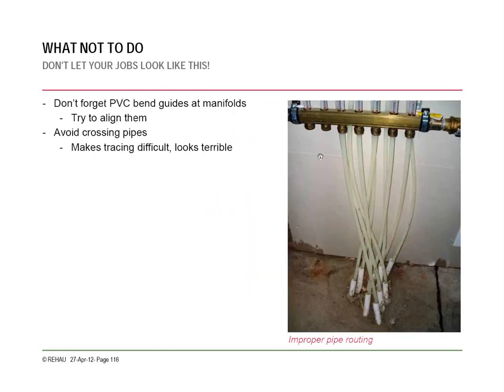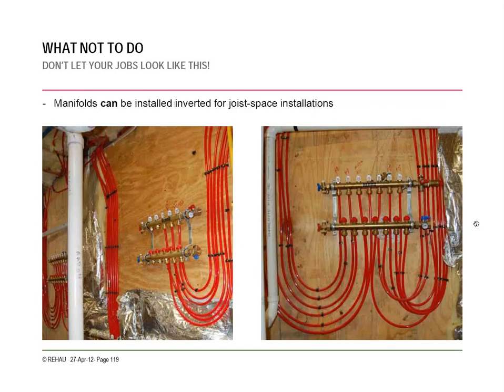Bring your pipes back in an organized fashion. Here you can see they just brought them all in a big group at the bottom. You can mount the manifolds upside down, so you don't need to be doing these giant loops like they did here.